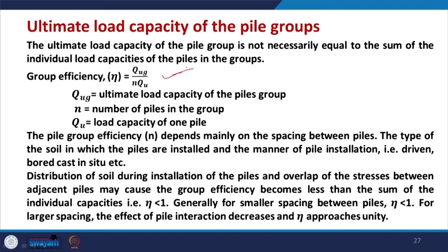The pile group efficiency eta depends mainly on the spacing between piles, the type of the soil in which the piles are installed, and the manner of pile installation, that is driven, bored, and so on. So, the value of eta depends on many factors, including the type of soil and the manner in which the pile is installed, and most importantly, if other things are constant, it is a function of the spacing between piles.